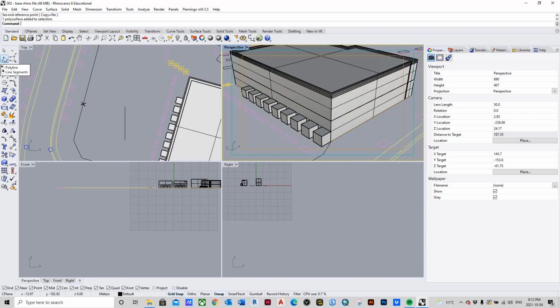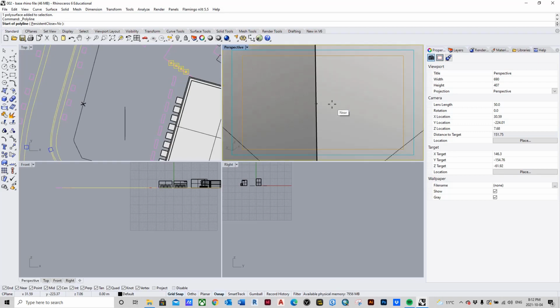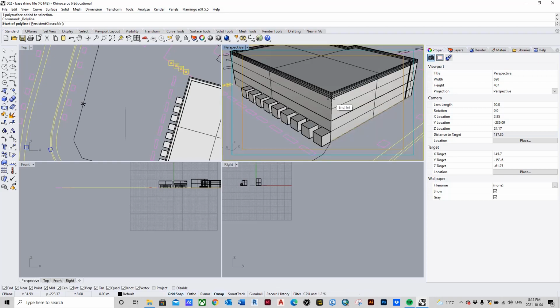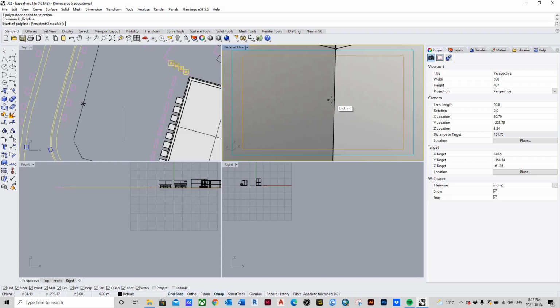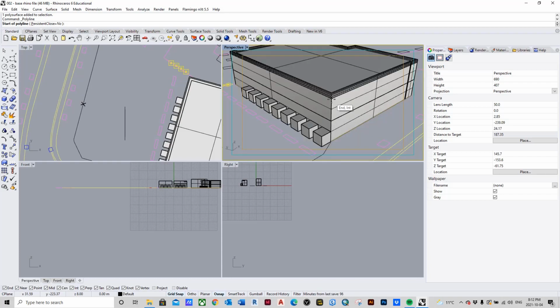We're going to use the Polyline tool to figure out exactly where that spot is. This is the way I like to do it anyway. So we'll select the Polyline tool, left click. We're going to move over to where we want to start our polyline. And since we want to move it down 1 meter from the base of the flashing, which is in here, we're going to left click and drag down.